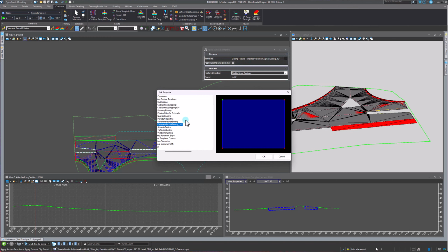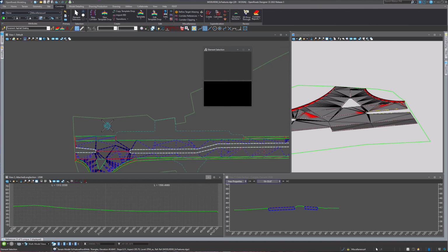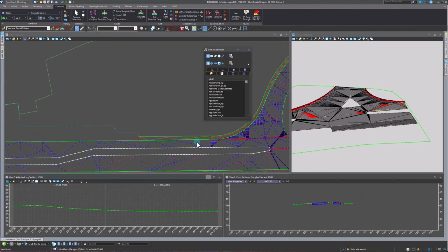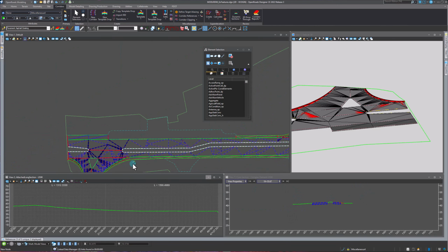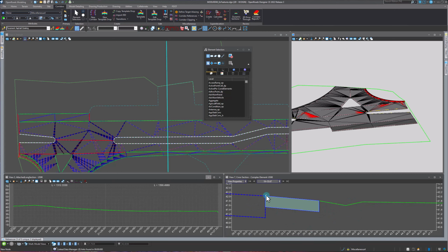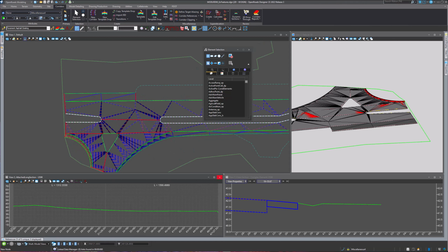So again, I've got to go select my paved shoulder existing. I've got that. So it looks a little bit different. They've got it set up so that the paved shoulder looks a little bit different. And if we come into our dynamic section view here, let's do this one real quick so we can see it. So again, I can just click through real fast. See, now I've got some shoulder depth that's showing as a different depth. So real quick, I'll go through and add the surface template to all of our terrains here, and we'll be right back.